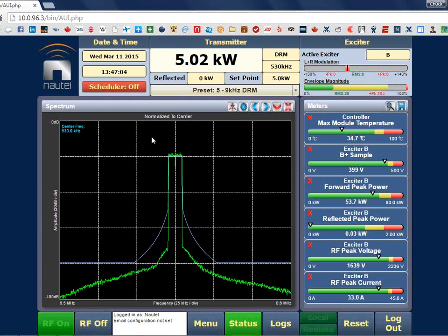In the shipping version, will the inductors in the output network be silver plated? No, they won't. We don't silver plate the inductors, because we don't find that the size of the conductor or the pipe there is already large enough so we don't have a problem with skin effect. Exactly. Okay. Are there 208 or 240 volt mains input options, especially in the 5 kilowatt model? Yeah, I think the 220 volt transformer that we provide has taps in that range.